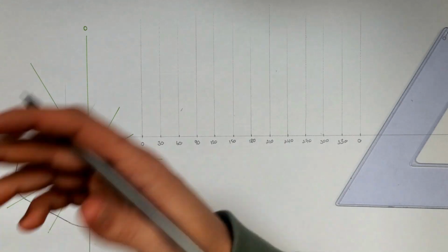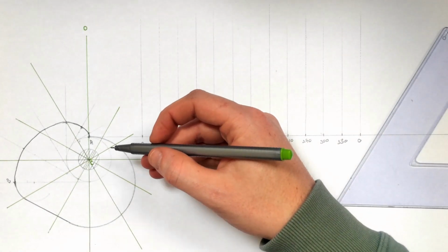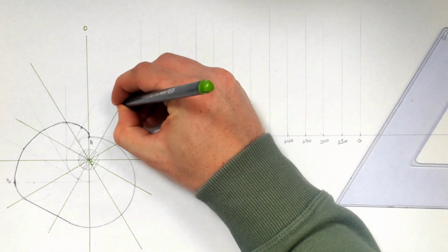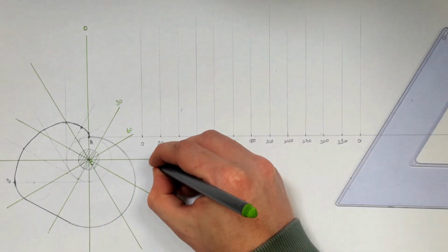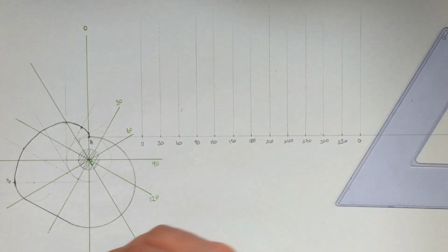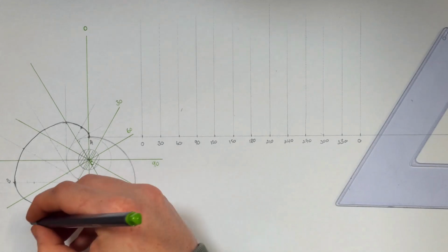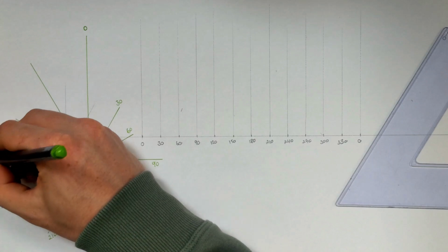If it says it rotates clockwise, then you label it anti-clockwise. So this is rotating anti-clockwise, so my first 30-degree section is going to be going in the clockwise direction. This one here will be for 60, this one here will be for 90. I'll zoom out there in a second, so we can get all those in.